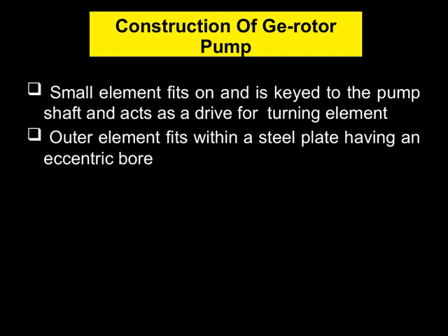Then we have the outer element, which fits within a steel plate. This steel plate isn't just a simple holder. It actually has an eccentric bore, meaning it's slightly off-center. This eccentricity is crucial because it allows for the movement and operation of the pump's internal components in a precise manner. Together, these parts form the core of the gerotor pump's construction, enabling efficient and reliable operation by ensuring the drive is securely connected and properly aligned within the pump housing. This design highlights the importance of carefully engineered components working together to achieve optimal performance.